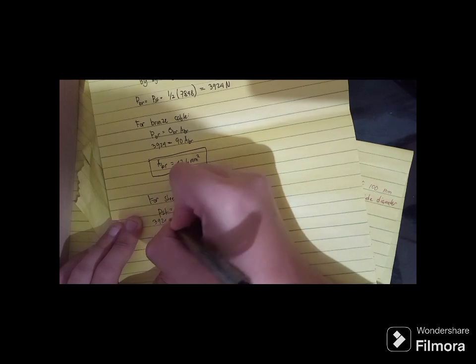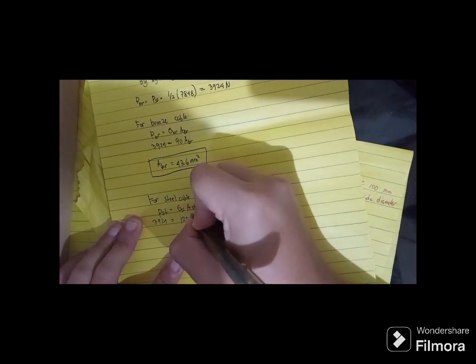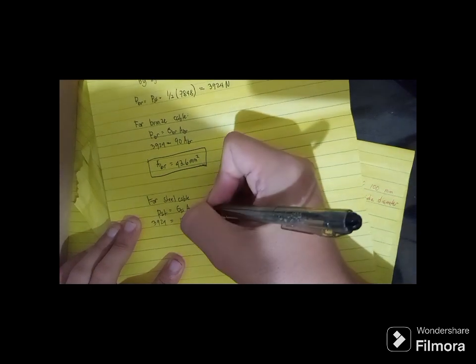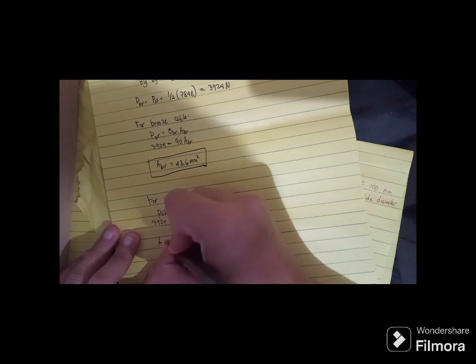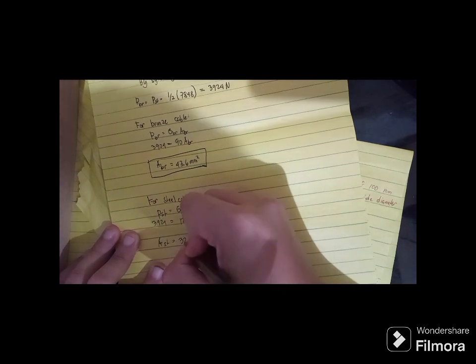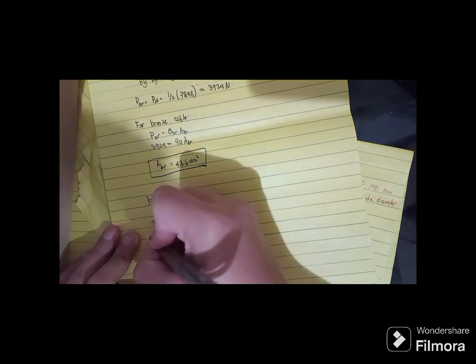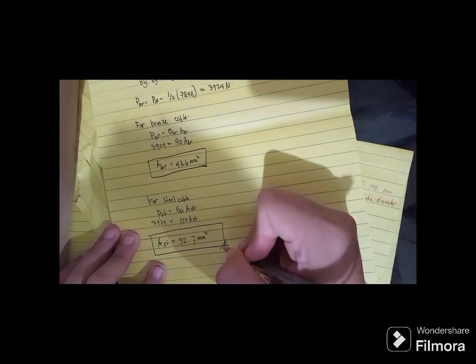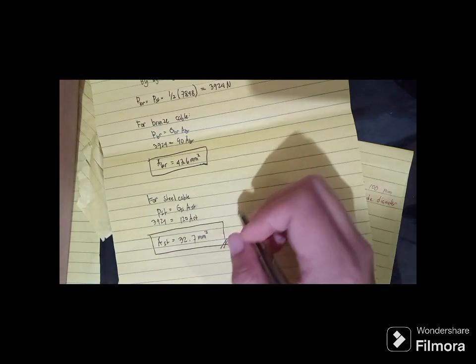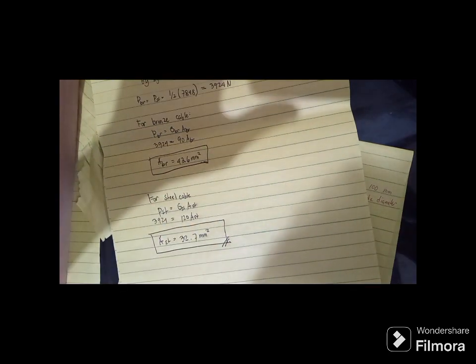So 3924 is equal to 120 times area steel. So we divide, and we have area steel equal to 32.7 mm squared. So we have here the answers for the area of bronze and the area of steel.